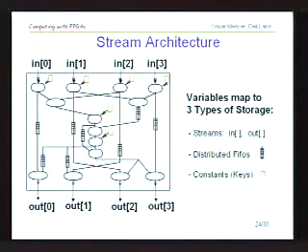The way this is done at the current moment, for the stream architecture, is that you have different kinds of variables. You can see in this structure there are 4 streams coming in, in 0 to in 3, and 4 streams coming out, out 0 to out 3. And you have other variables that are intermediate variables that just connect the nodes inside of your data flow graph that we want to put down into the FPGA.